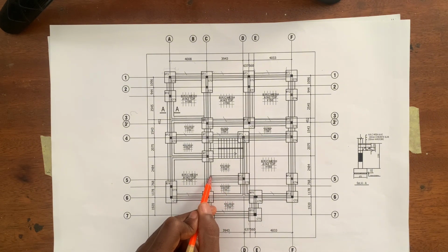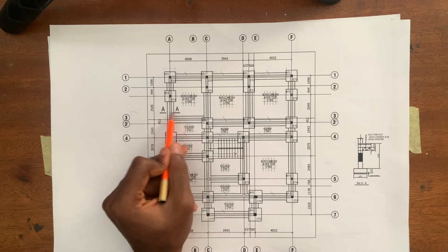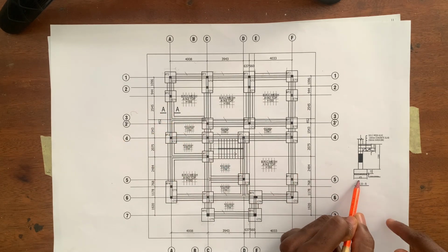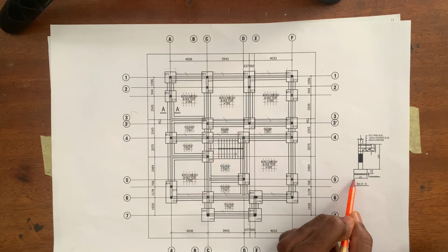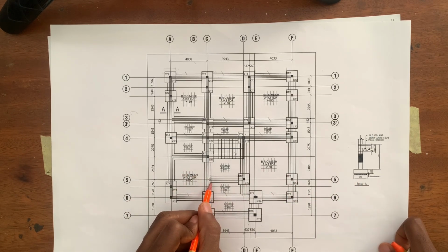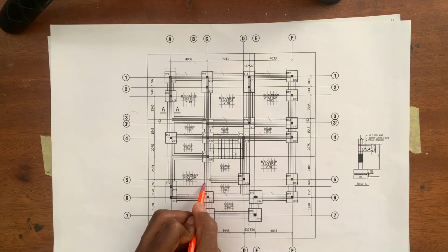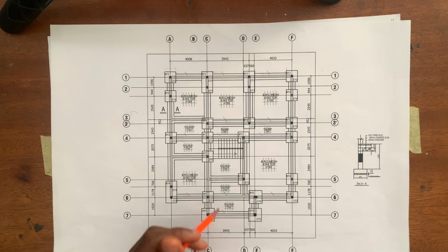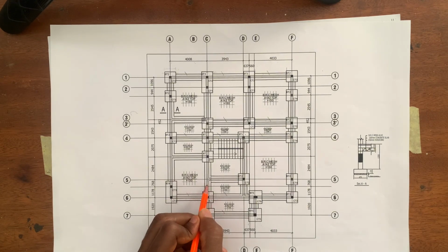Similarly, we need to determine what is the width of the trench. Now if you look at this, we have a section here through AA at the trench, and this is the section here. So if you zoom closer, you can see that this dimension for the trench from here to here is 675. So it means that the dimension for this width from here to here is 675, but that's not what we're looking for. We're looking for half, because the orientation for C is at the middle of the trench. So half of 675 is going to give me 337.5.